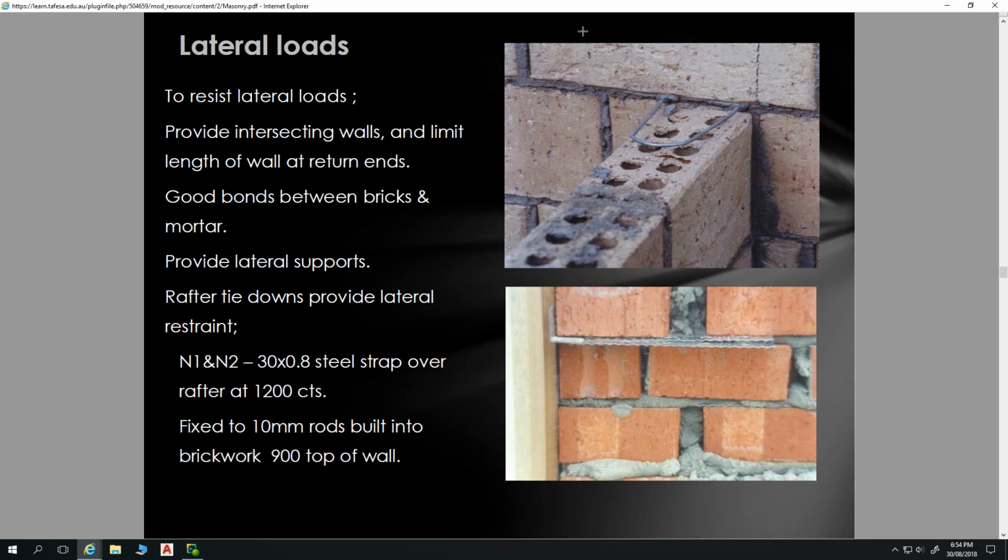So after they welded, they didn't clean up and they didn't spray any galv. Yeah, so they could have sprayed cold galv on there or something like that. Painting. Yes, yeah. But they didn't do that. That's why that happened. They didn't know. Yeah, and I think that's a really good point actually.